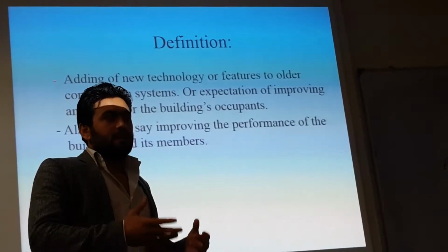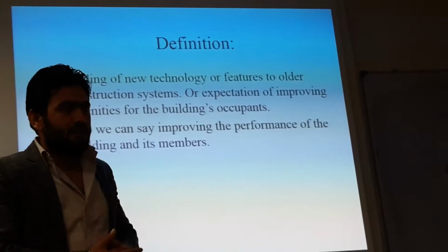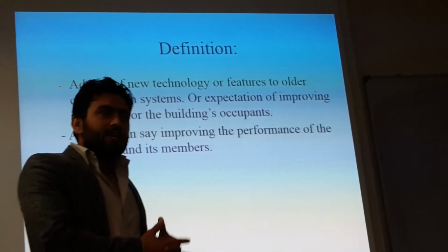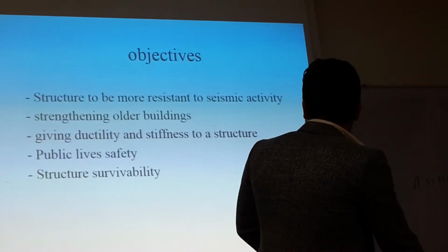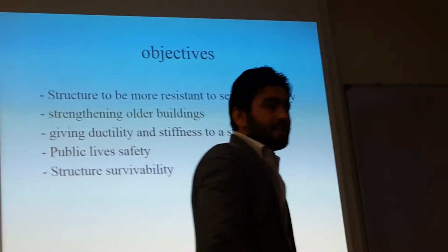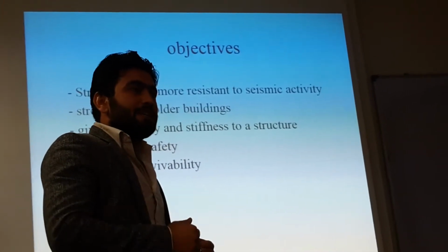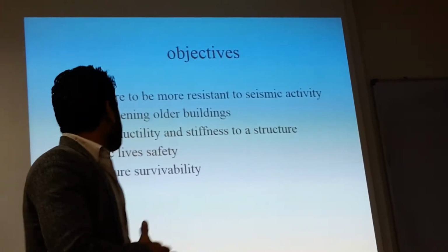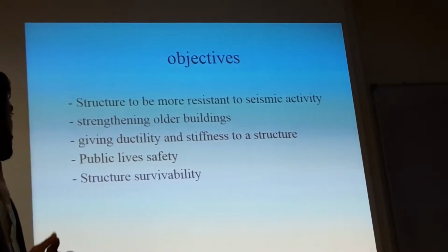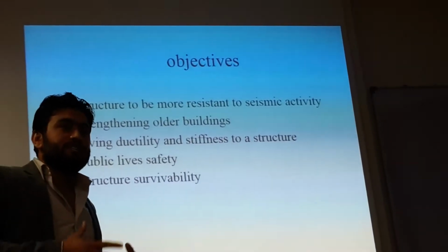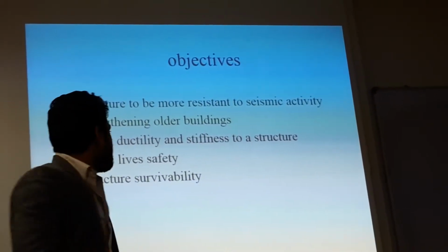Retrofitting is adding new features or materials to existing buildings to resist lateral and vertical loads. That is a short definition. In the objectives, we can say why we do retrofitting: to resist seismic loads and seismic activities, to give strength to the building, and to improve its ductility and stiffness. There, retrofitting is needed.